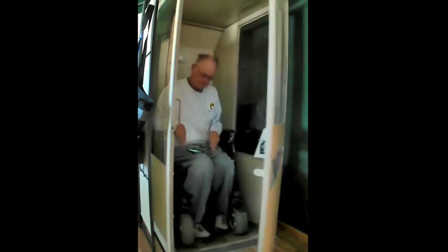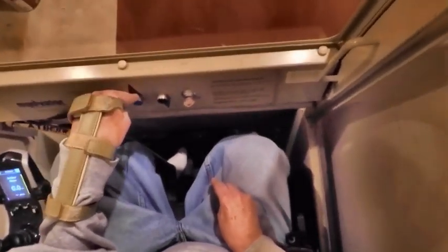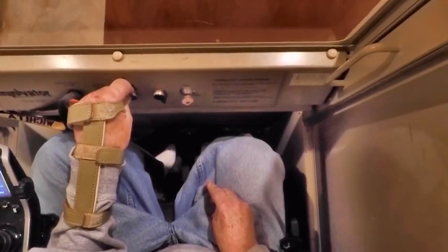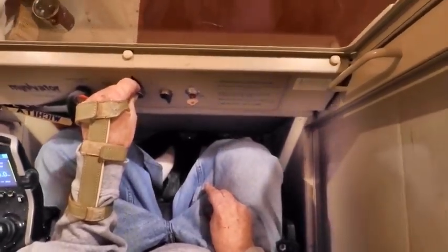There are switches that sense the travel at every level to assure the carriage always stops when the two floors are lined up perfectly. There are also switches that limit any elevator movement if the door or curtain is not completely closed. Many home elevators require a constant touch to the up and down switch in the carriage, and if the finger pressure is released, travel will stop.